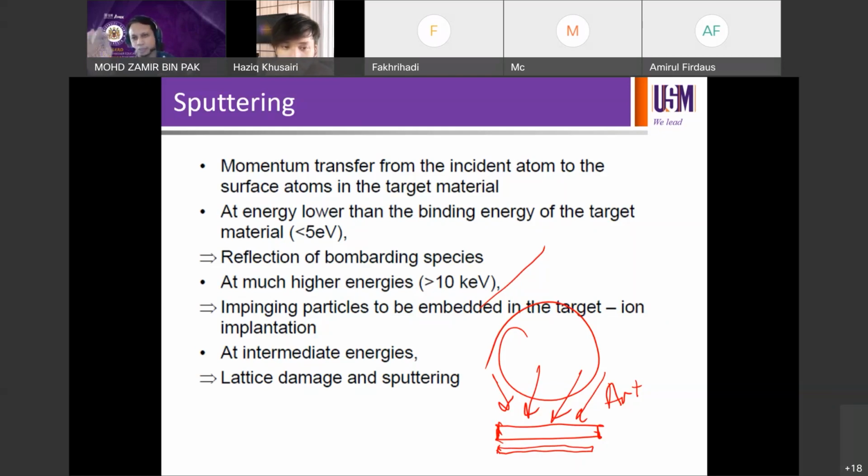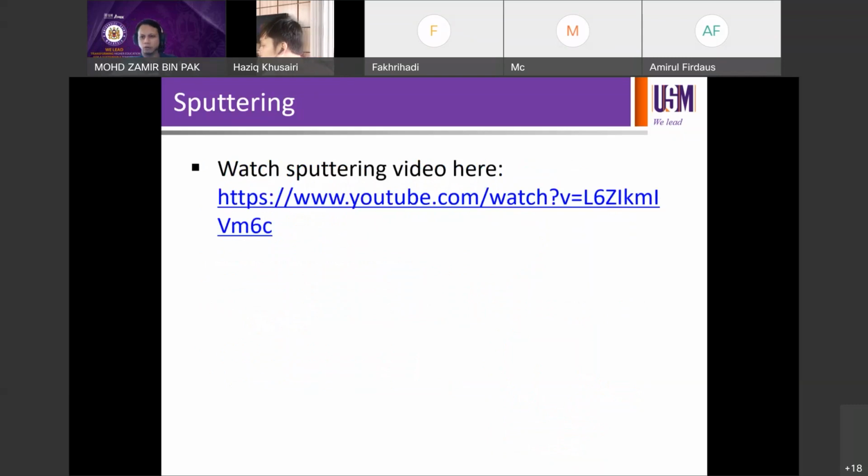So you sputter, but then you are actually etching. But that is not etching literally as we learn in anisotropic, isotropic, dry, wet, all those things. But it's actually etching, as long as you remove something, it's actually like etching. Okay, but we call that sputtering. Okay, over time you will get thinner and thinner and thinner. If it gets thin enough, then we have to buy a new sputter target. Otherwise it will become brittle. Okay, you can watch this sputter video later on.